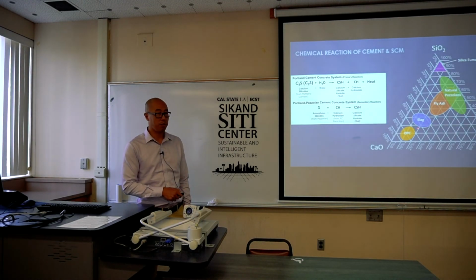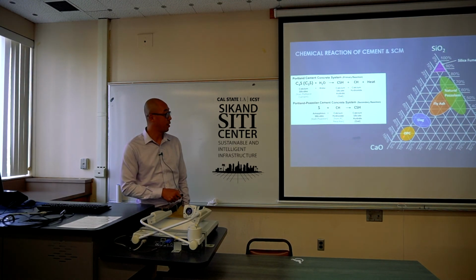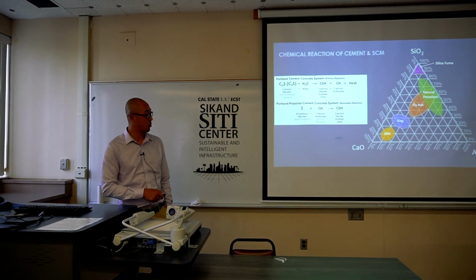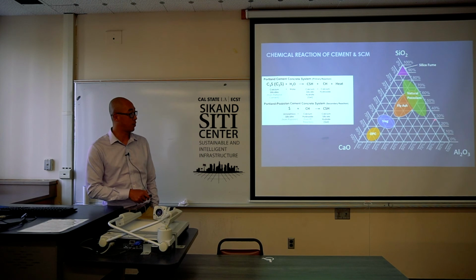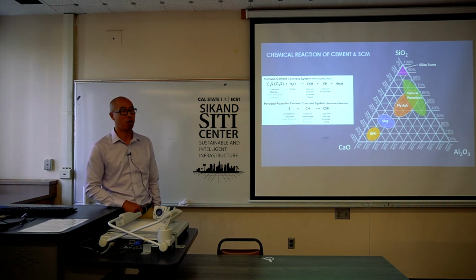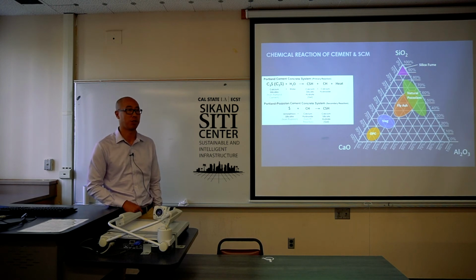Yeah, as you can see from these plots, there's the fly ash, and there's the Portland cement. Slag is closer to Portland cement, and it only has about 20% silicon phase, so it can react with water similar to Portland cement. Fly ash may have too much silicate in the material, so you may not have enough calcium to gain strength. But for slag, I think the strength, not early strength but maybe long-term strength, would be similar to conventional concrete.